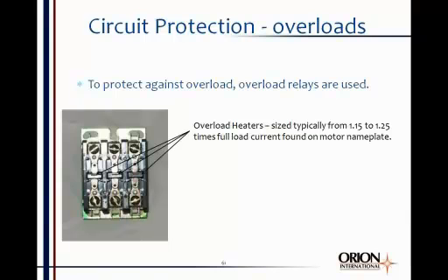It'll try real hard to do 10 horsepower worth of work, and the current will get much, much greater than the motor's designed for, and the motor will either become damaged or it'll go into locked rotor or something will happen. And typically motors can't turn more than the rated amount of work. You can't get more work out of them than they're designed to put out.